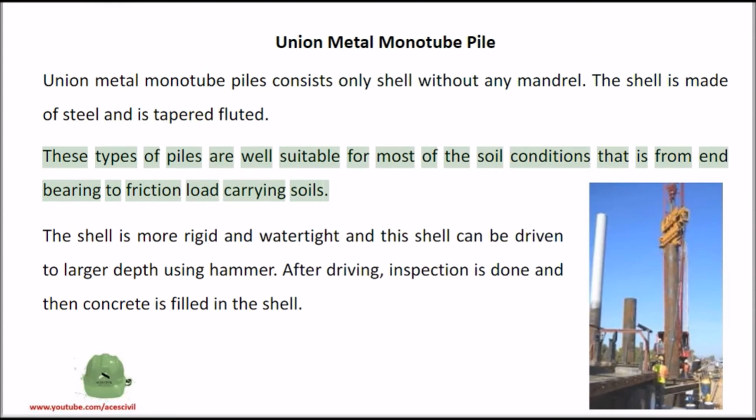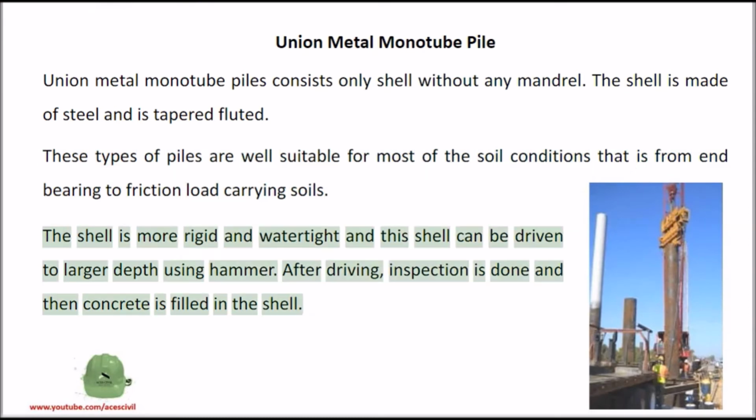These types of piles are well suitable for most of the soil conditions, that is from end-bearing to friction load-carrying soils. The shell is more rigid and watertight, and this shell can be driven to larger depth using hammer. After driving, inspection is done and then concrete is filled in the shell.